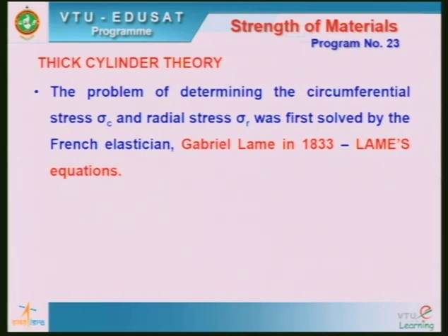Now, this problem of thick cylinder was first attempted by a French elastician, Gabriel Lamé, in 1833. His objective was to determine expressions which can give you values for the circumferential stress and the radial stress in the wall of a cylinder at any point. And these expressions are generally referred to as Lamé's equations.